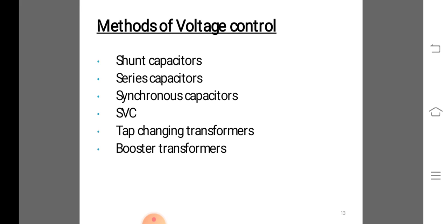control. These devices consist of shunt-connected static reactive elements, that means linear or non-linear reactors and capacitors, configured into a VAR compensating system. Some possible configurations are shown in the figure on the next slide. Even though the capacitor and reactor are connected to the low voltage side of a transformer, as I mentioned in an earlier slide, the capacitor banks may be distributed between high and low voltage buses.